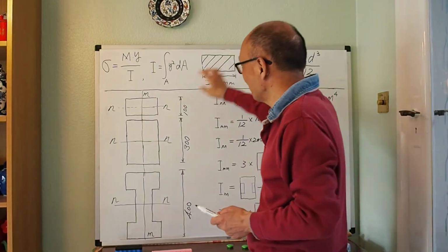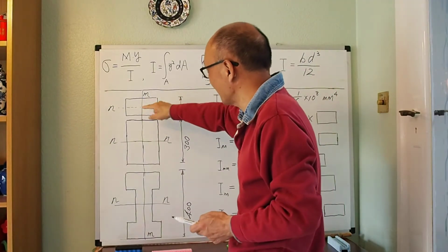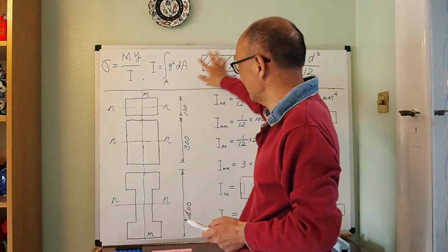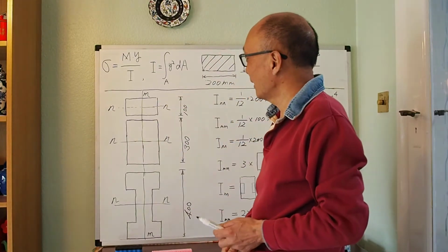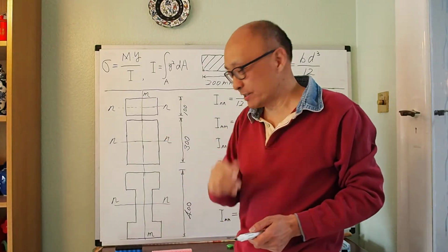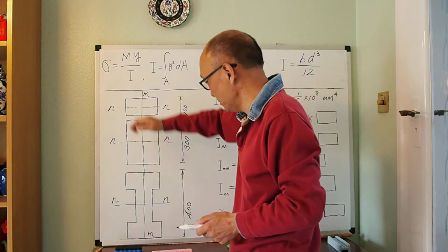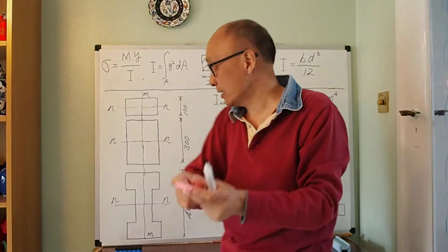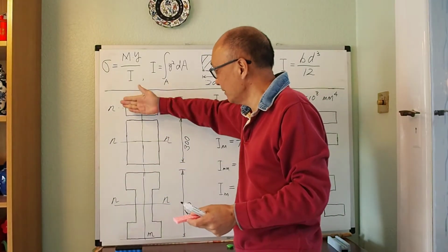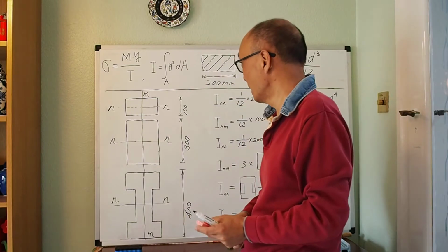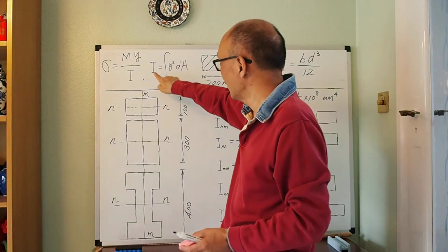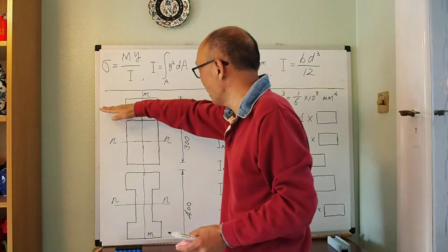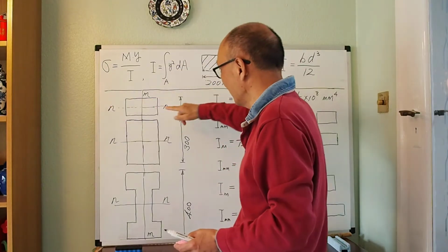I'm drawing this case again here, so I'm going to compare different cases. My first case is just this. Now let's consider two different scenarios. In one case, this beam, just like that beam there, bends in that way, yeah? So the beam bends in that direction. So I'm calculating this I, the second moment of the area of this area, about this neutral plane, N.